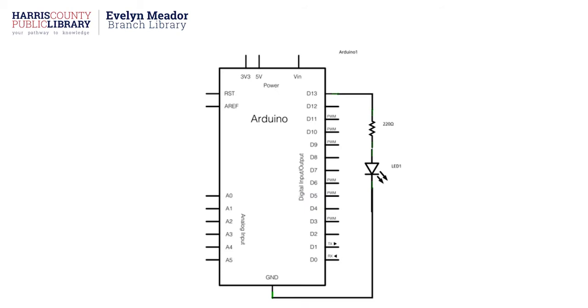Here is a circuit diagram. If you look at this image, you'll see it's an Arduino pinout, and you'll see that D13 right up there. They've got the ground at the bottom because, again, this is a circuit diagram, not an actual image. You'll see there's a wire going from D13. There's a little squiggle there, and it says 220 ohms on the side. That stands for the resistor. And then that little triangle with the arrows, that signifies an LED.